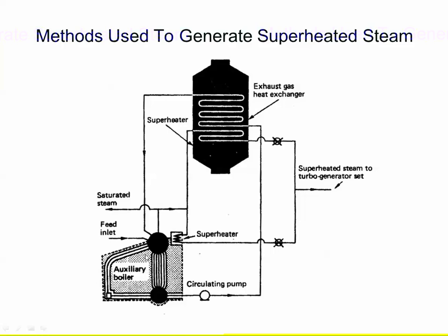Now, if I move it with the economizer, this is the lowest temperature. So it's going to be giving up its heat as it goes through the generating tubes. Back here, this gas is well below the melting point of steel. It's quite low, actually. And as it goes through the superheater, that will pick up some more heat.